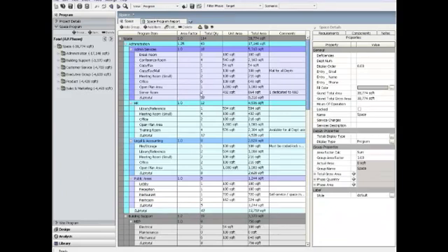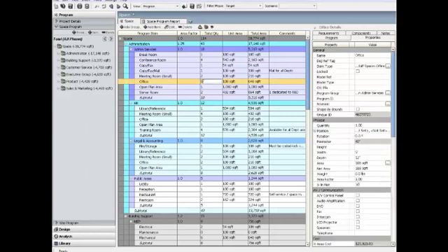These views can be customized to display different columns that contain Affinity properties and requirements. Here we're looking at the space program items, both departments and rooms, and the area factor, total quantity, unit area, total area, and comments for each. I can quickly and easily make changes to the column values by entering them directly in the cells, like this quantity requirement. Notice the changes to the quantity or area of my spaces will automatically recalculate the total area for the program.